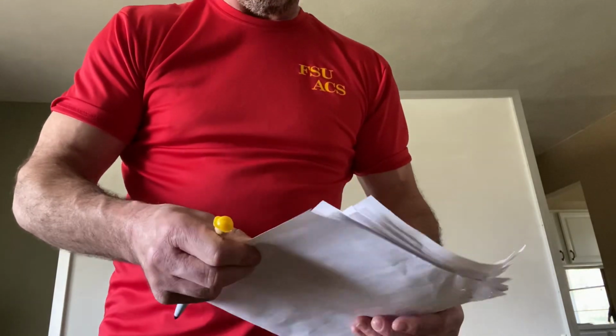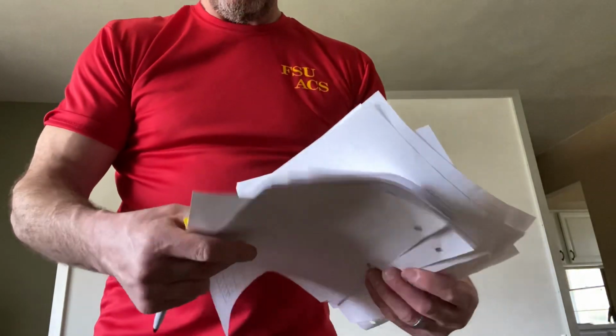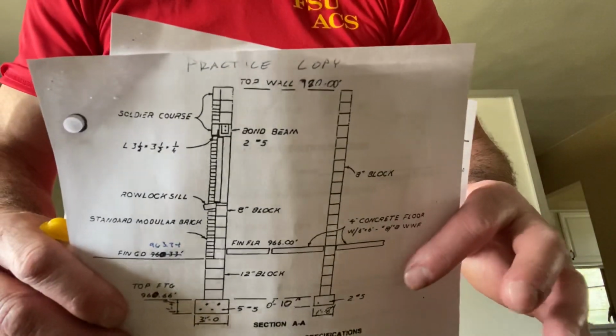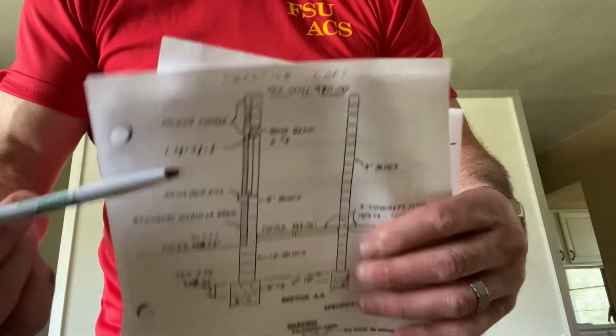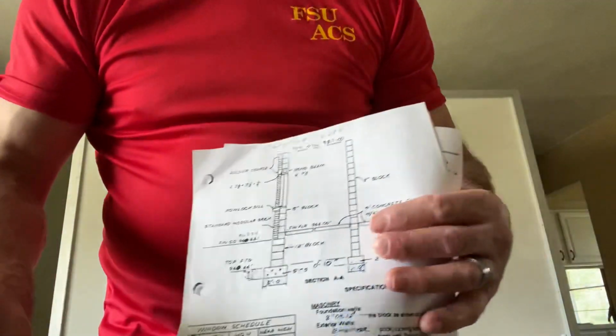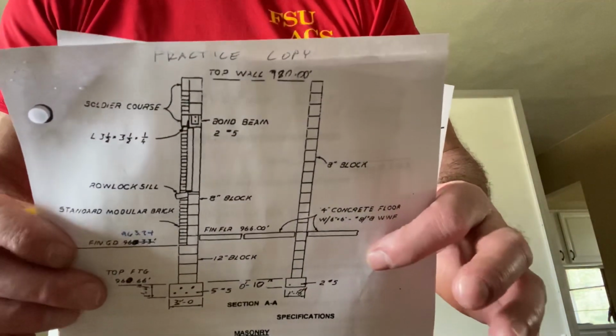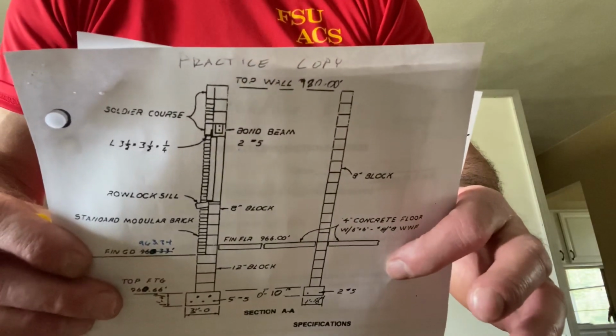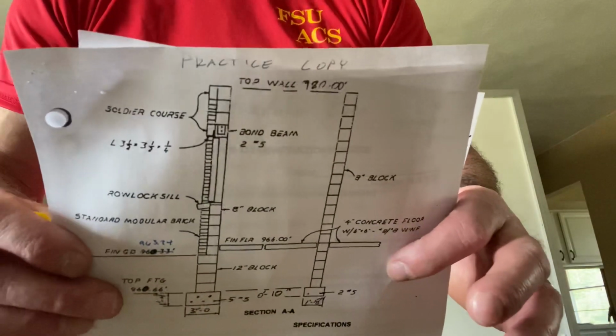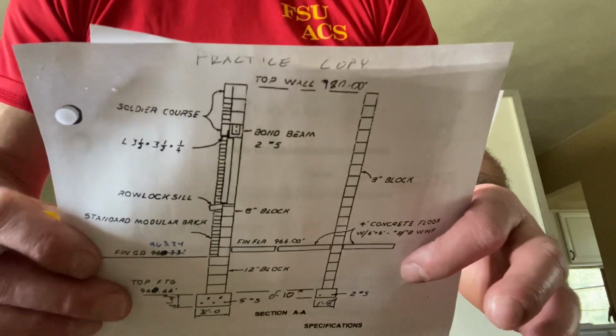As I look at my print, if I look at my section cut right here, I can see it. It says there's my bond beam right there. It shows me bond beam. It shows me the rebar inside that bond beam, and then that would be grouted full. Again, it's at the top of the highest opening, which is our big overhead door. All right, so what do I need then?